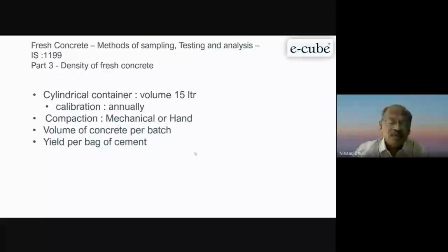When you are working on a project, at the end of the project, after 6 months, you reconcile the concrete requirements, and as per drawing, you will find that I have to use 5,000 cubic meter, but at the end of the project, I used 6,000 cubic meter or 5,500 cubic meter. Now, who is the culprit? So, at a certain frequency, maybe every month, you have to do the reconciliation of concrete, whether you are buying from outside or producing from your own batching plant.